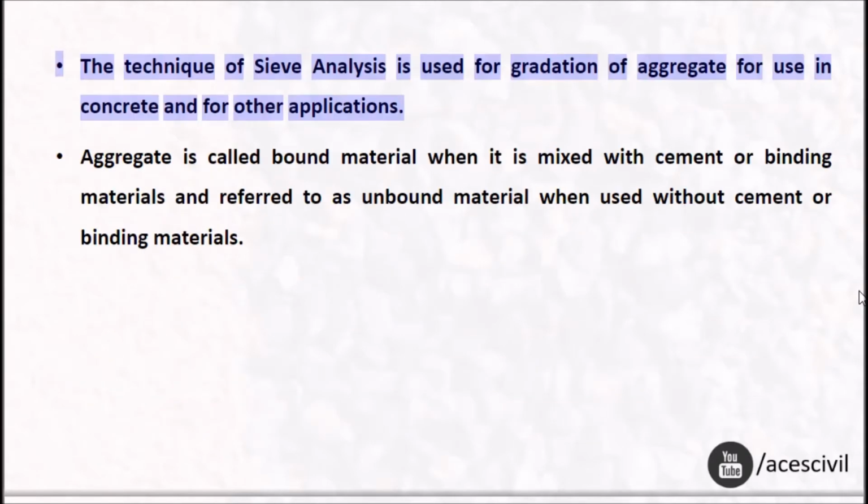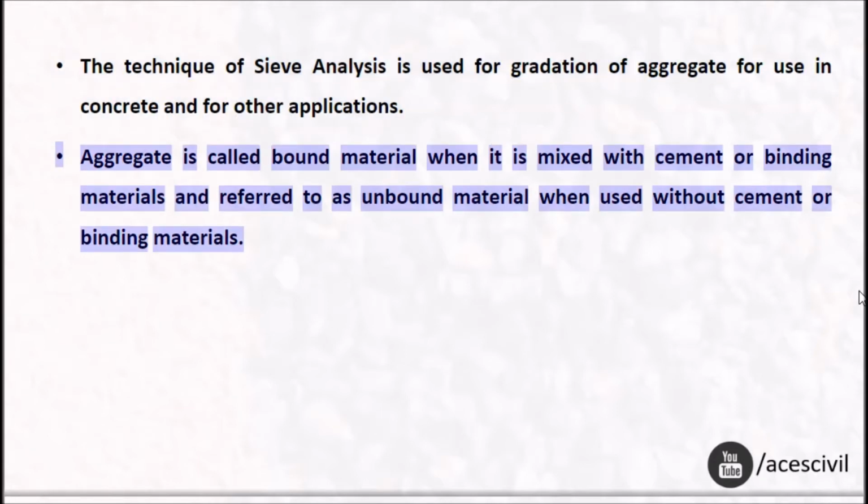The technique of sieve analysis is used for gradation of aggregate for use in concrete and for other applications. Aggregate is called bound material when it is mixed with cement or binding materials, and referred to as unbound material when used without cement or binding materials.